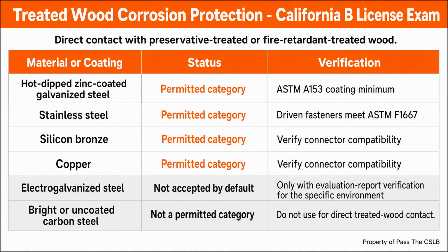Treated wood contains chemicals that can be aggressive toward unprotected steel, especially when moisture is present. Corrosion can progress along the buried shank where a quick surface glance does not reveal the loss. The immediate condition is not always a dramatic red stain at the nail head. The hidden section of the fastener can be the part losing metal. That is why the word galvanized needs a follow-up question.